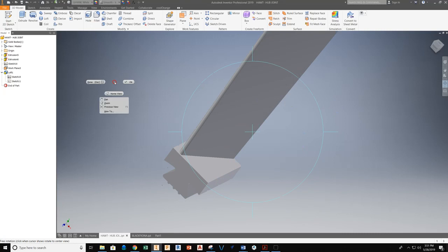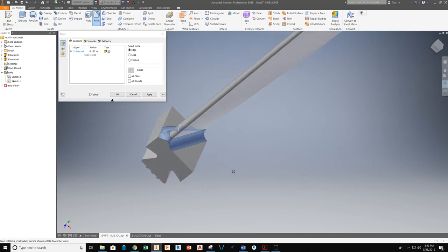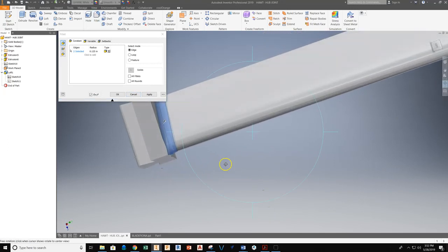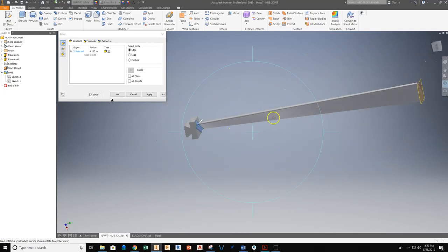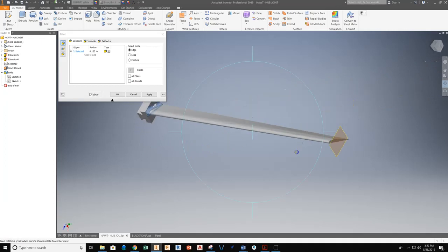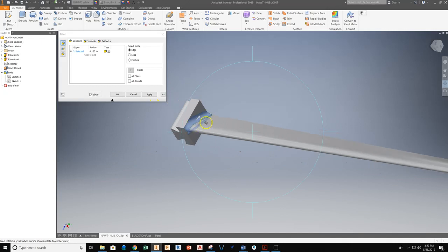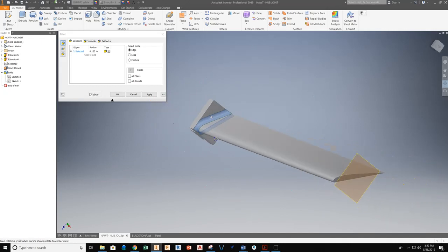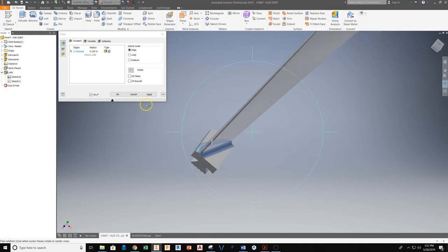One of the things that we can do to add some strength is to add a fillet down here along this front edge. By adding a fillet along the front edge at the base here, it's going to add strength and stability to the system and to this blade. By doing that, any type of vibration that is going to occur can be mitigated from actually turning into a crack or a break in our 3D printed part. So something I'd highly recommend doing there is to add a fillet to the foil at the joint hub.